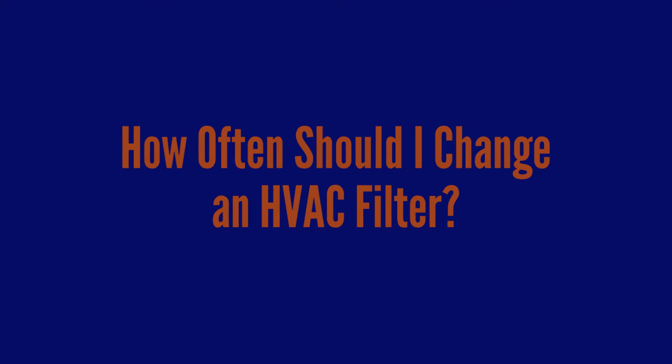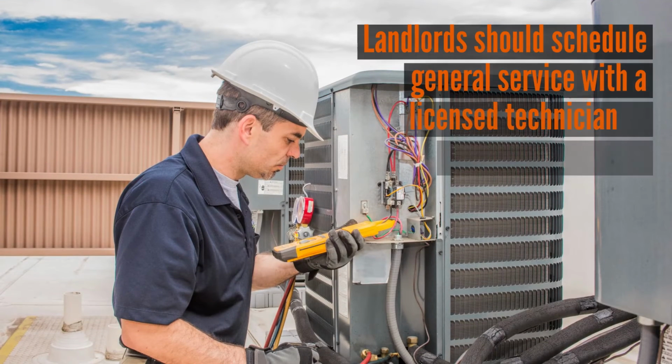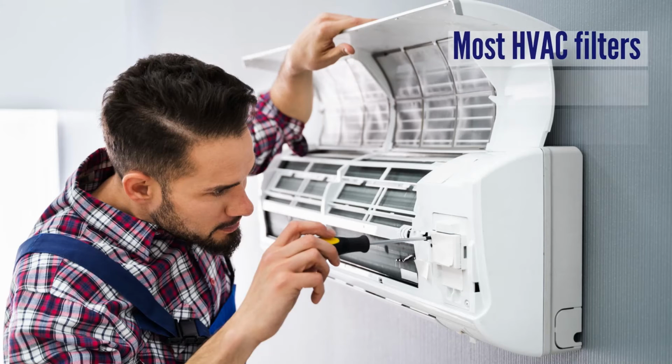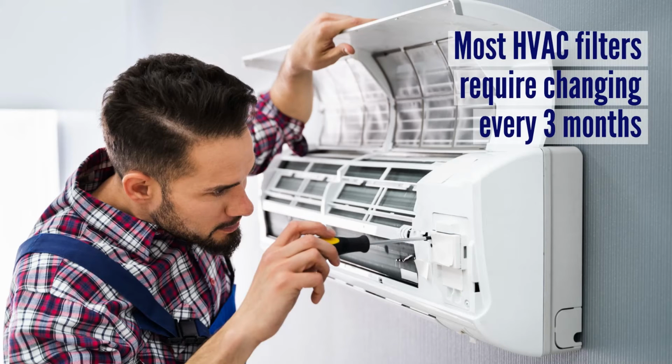Proper maintenance throughout the year is critical, and landlords should schedule general service with a licensed technician at least once per year. But as far as changing the filter, the frequency will depend on several factors. On average, most HVAC filters require changing every 3 months or so. However, let's review some other considerations.